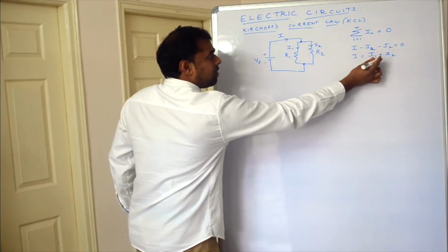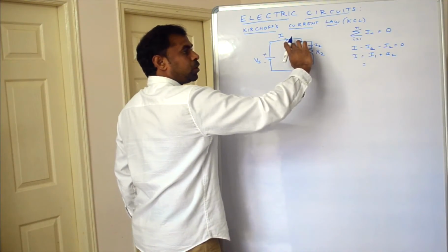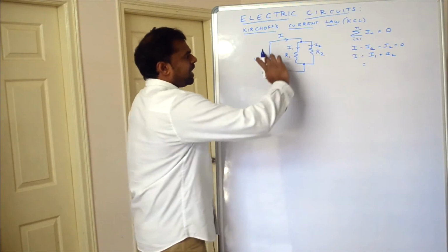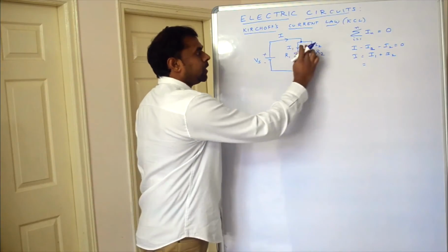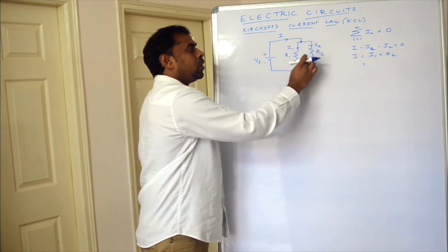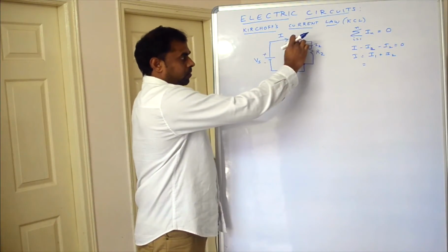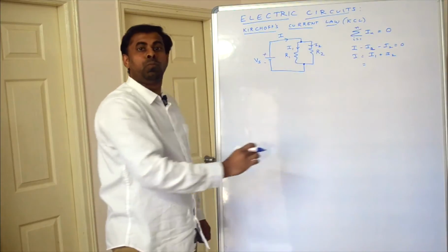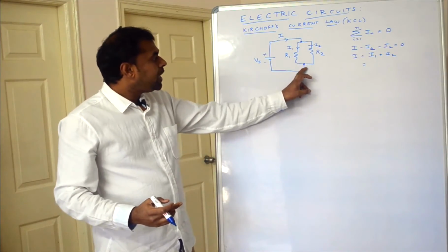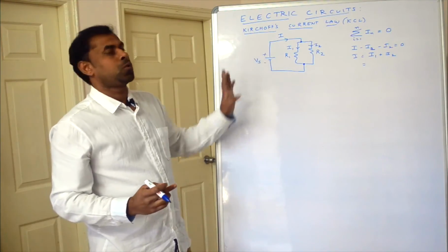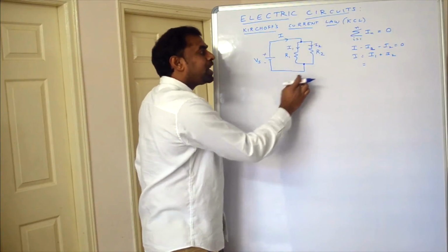I1 is nothing but the current flowing through resistance R1. Same voltage is applied across both the resistors. If you see, these two resistances are having two common junction points. The current coming here will pass through both the resistors by dividing and will join here and flow back to the source. Here for the current only one entry point, one exit point is there.